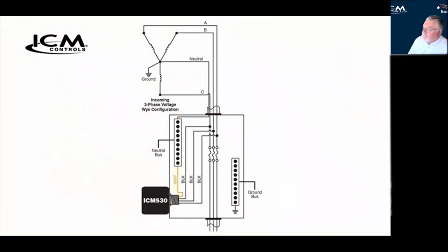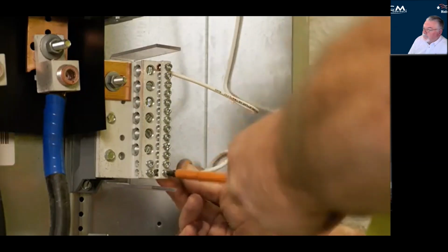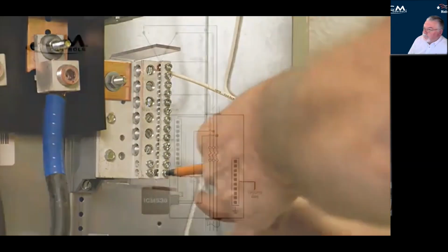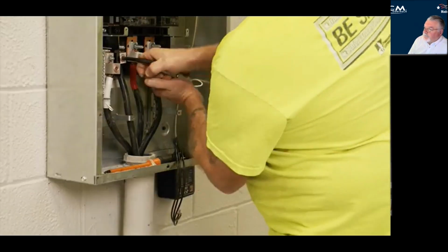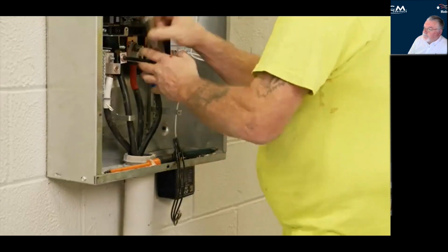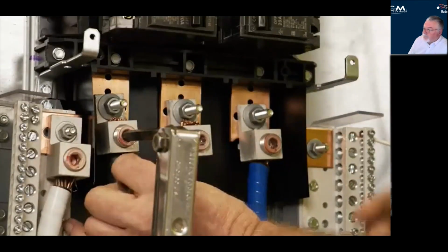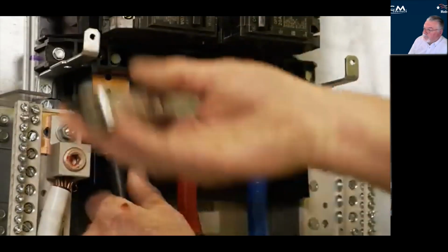Connect the white wire coming from the surge protective device to the neutral terminal in the distribution panel. Connect the 3 black wires from the surge protective device in parallel with the 3 incoming line wire terminals in the distribution panel. The black wires are not specific to L1, L2, or L3 and can be installed in any order.